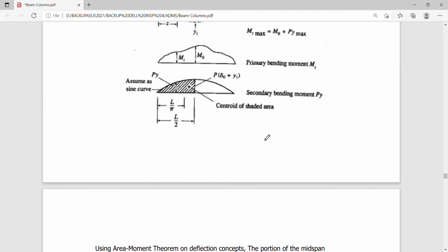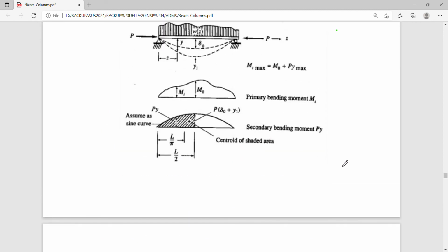So if you still remember your tangential deviation, wherein if I make a tangential line at point, let's say B, I get the deflection here because this is a maximum value. So this slope is 0. So my maximum deflection here is this one here.